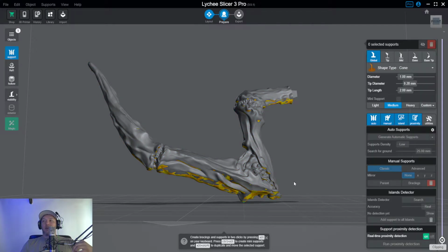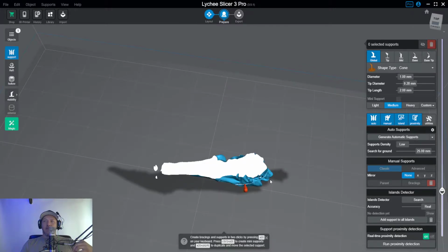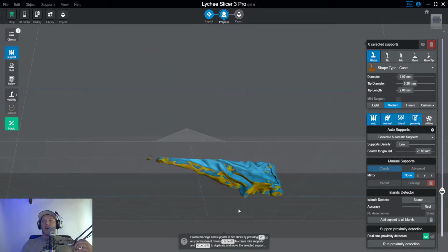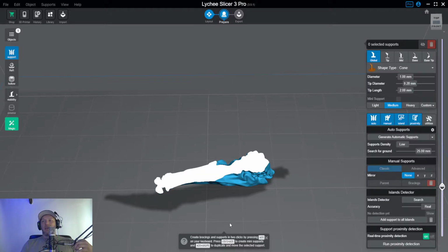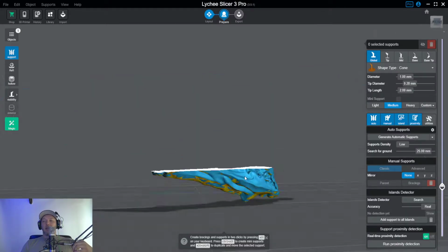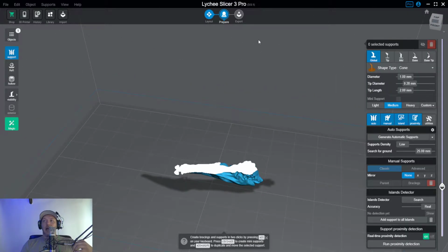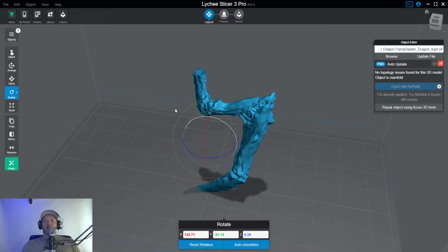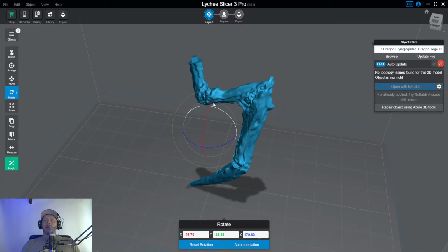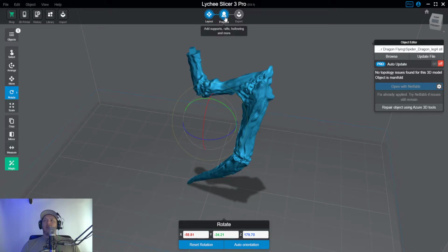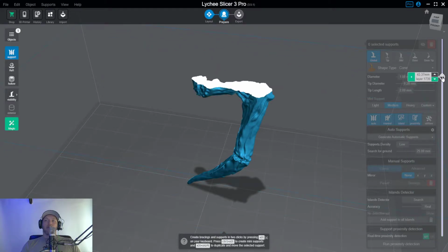surface area during print. So once we get to about these layers, all of a sudden we have a pretty wide surface area that our supports are going to have to maintain, and we really want to be sure that that doesn't pop off the build plate. So we're going to have to toss a bunch of extra supports here. I prefer to put as few supports as possible. And in this particular orientation, we might see a little bit of extra surface area up here at the top.